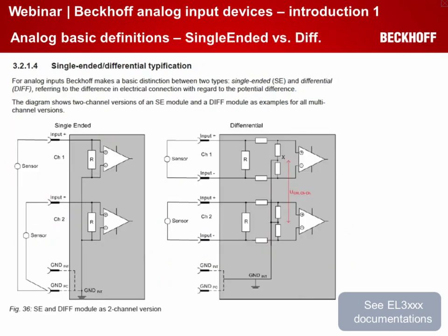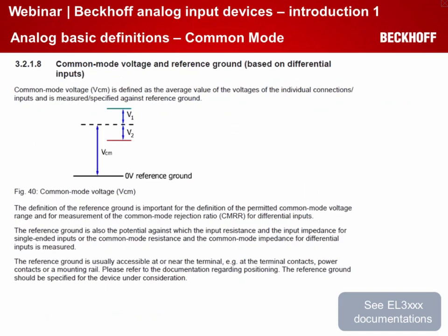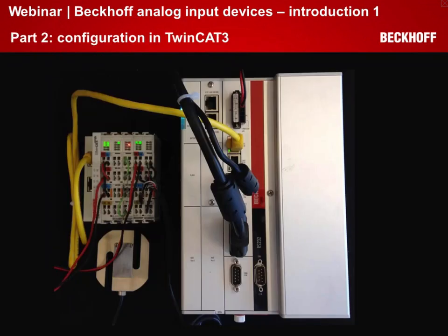Another point is the single-ended and differential difference. Most of our terminals you can have in a single-ended or in a differential version, because this is often very useful in an automation area to have lower wiring costs, and so the internal differences are explained here. Common mode voltage and reference ground is also here an own chapter. Okay, now we have the theoretical part, and I hope with these hints you can select from the Beckhoff website, from the catalog, the module that fits into your